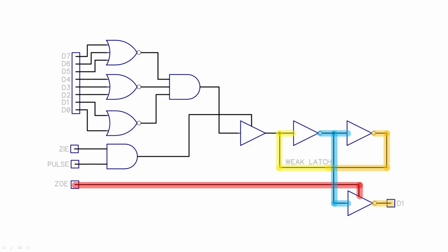Now, if you're doing the skip instruction, the program counter will get fed into the A register. This signal would go out to the B register, and D0 and D2 to 7 will be held to 0. The 0 flag will be fed out to D1. Thus, the byte in the B register will either be a 0 or a 2. And you're going to add this to the program counter. So you either skip forwards 0 bytes if the 0 flag was 0, or you skip forwards 2 bytes if the 0 flag was a 1.